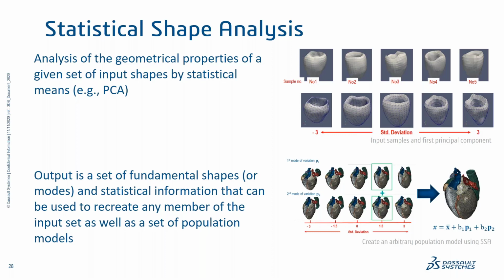So in this case, one of the limitations with traditional statistical shape analysis, if you're just doing it with nodal coordinates or FEM coordinates, right, is one, your FEM mesh can get easily distorted and give you poor simulation results, and two, that's a lot of parameters to look through. Yeah, you can get very accurate shapes, but that's a lot of parameters in your model library.